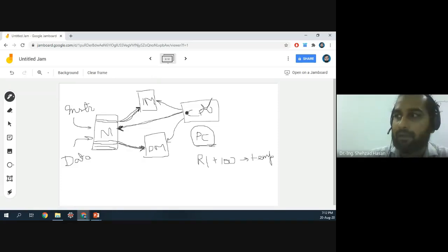And once populated, the CPU can perform these two operations simultaneously. All the program counter values are going to be searched in the instruction cache, and the other values are going to be searched over here. If the value is found, it can be returned to the CPU, and if the value is found over here, it can be returned to the CPU. And both of these tasks can happen in the same cycle.